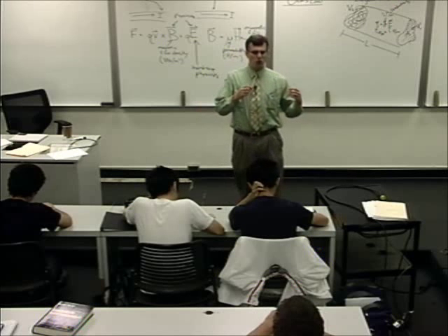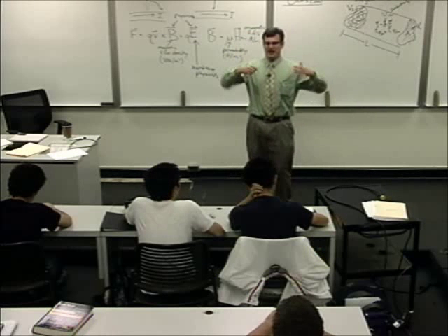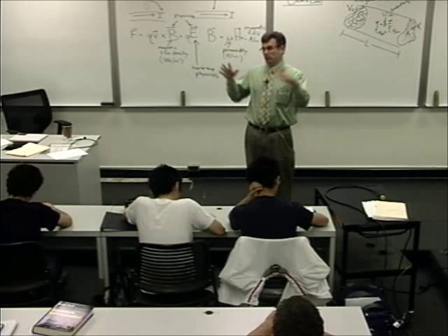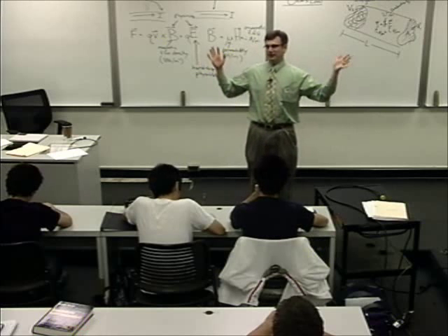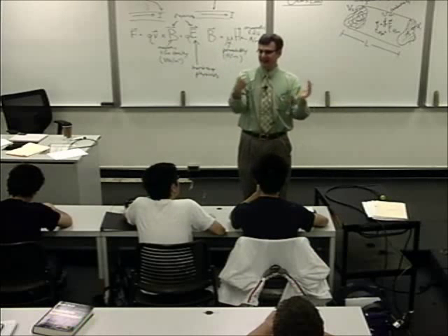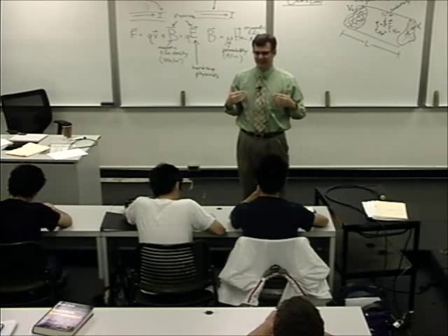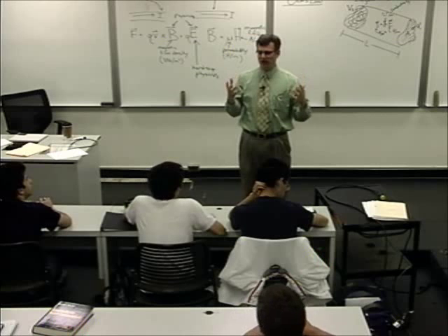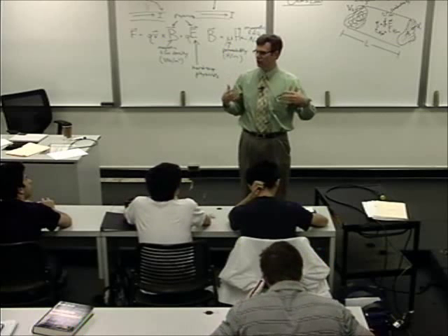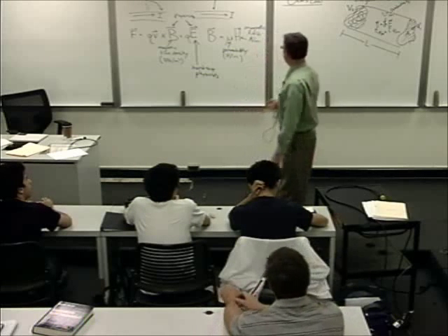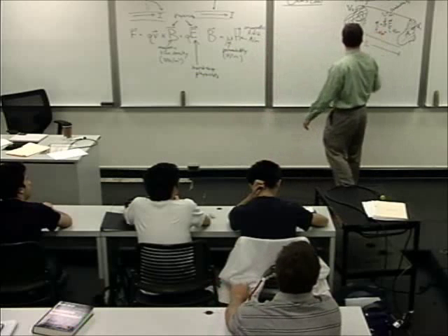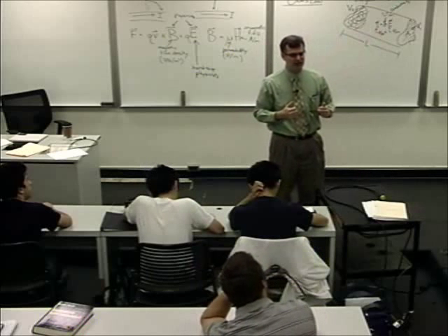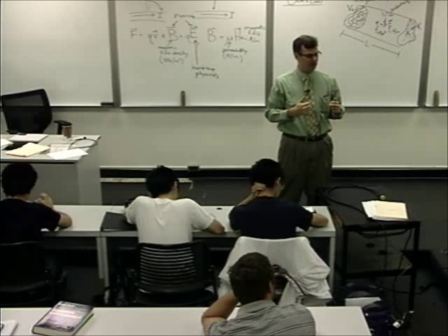But of course, what happens when that happens in material? They accelerate, and shortly thereafter, they crash into something. And they're shaken up, they bounce off, they shake it off, and they start accelerating again, and they crash into something. So statistically, depending on how much stuff is in the way and how many free electrons there are to crash into stuff, you'll get a value for sigma that represents the average net flow of current density, amps per meter squared.